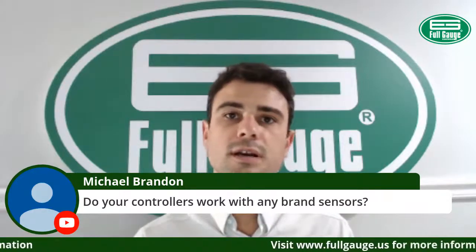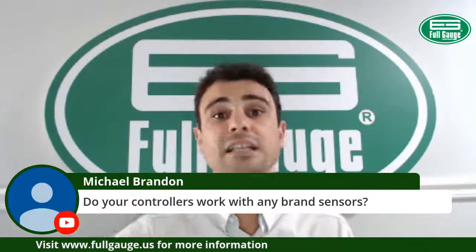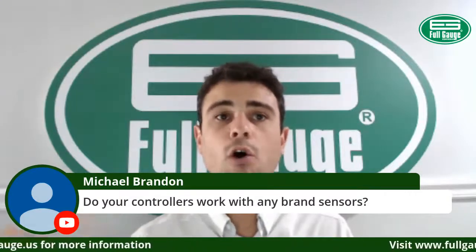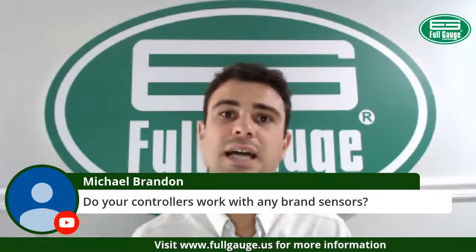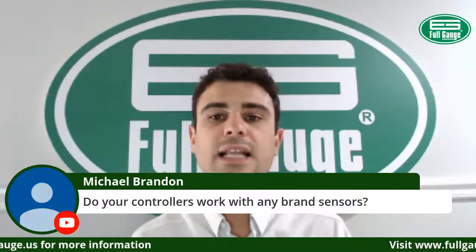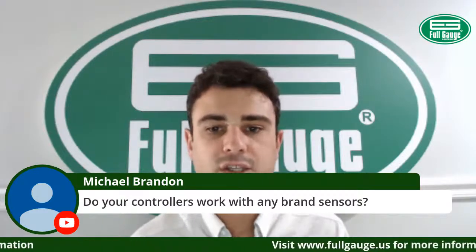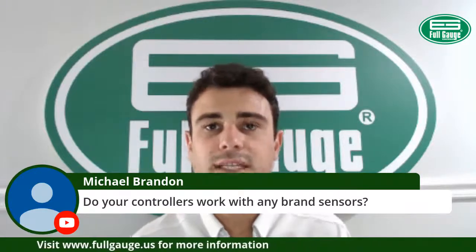The sensor reads a certain temperature when it is at a certain resistance in ohms. Most controller manufacturers use 10,000 ohms at 25 degrees Celsius. That's what we have for our temperature sensors. Our temperature sensors are 10K at 25 degrees.